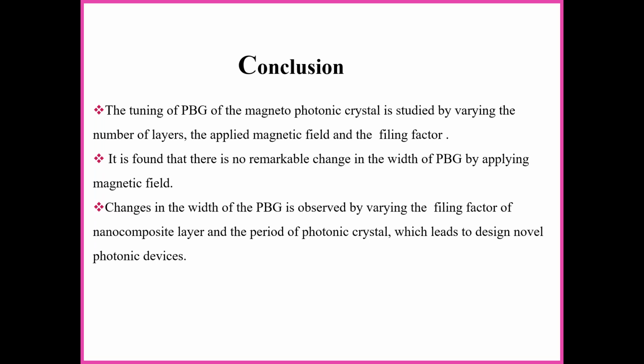In solar cells, we need an intermediate reflective layer. For that only we are using this, and we can also use this for anti-reflection coating and also DBR, to localize the light inside the crystal, inside the solar cell, hence to increase the efficiency. If the light is localized inside the solar cell by some means, by using this magnetophotonic crystal or other photonic crystals, we can reduce the reflection. In the distributed Bragg reflector, we can increase the reflection. Then in the IR layer, the main purpose is to use it as an intermediate reflective layer. There, reflection is possible to create more electron-hole pairs. Therefore, we can increase the efficiency of the solar cell.